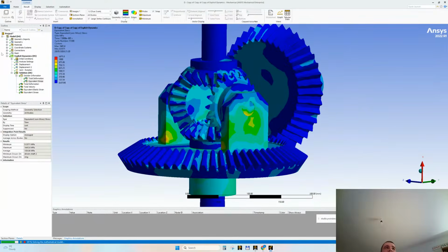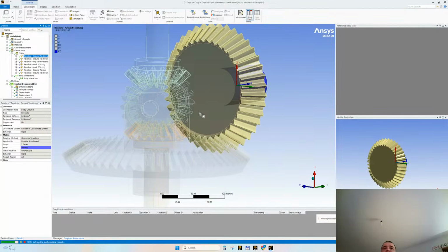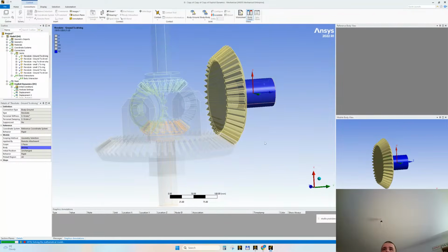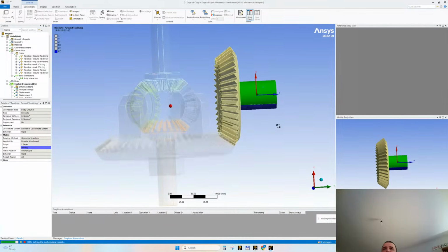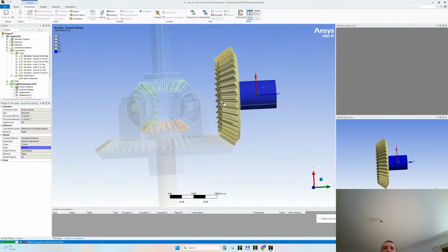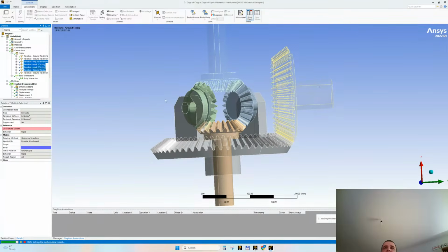So I showed that we only need to restrain the driving and the driven. Yeah, these pertaining to the housing and this which comes from the gearbox, engine, clutch, gearbox, yes. And with the explicit dynamics, everything is taken into account, yes. So you can forget about all this because we have contacts.